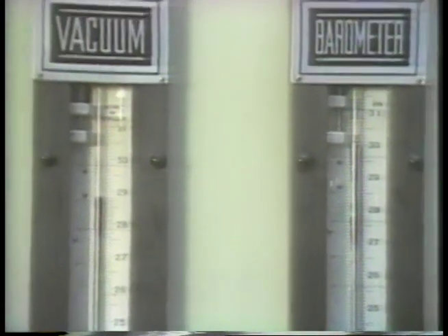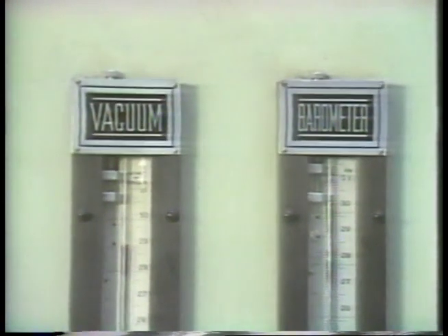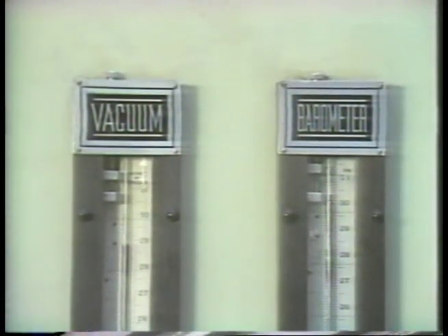Now, in order to find the actual pressure in the condenser, or the back pressure, it's necessary to make corrections for variations in atmospheric pressure. To make these corrections, we use a manometer and a barometer, which you'll find in most control rooms. First, we take two readings, one from the manometer, measuring the inches mercury vacuum in the condenser, and one from the barometer, measuring atmospheric pressure.